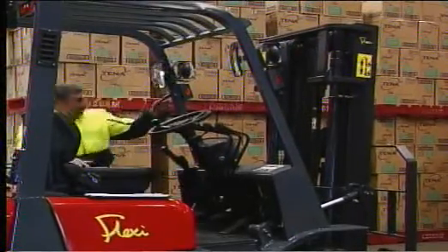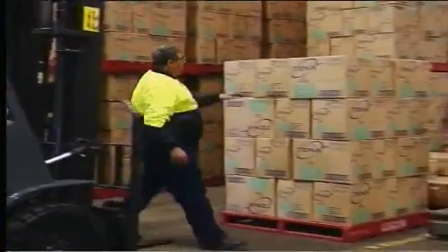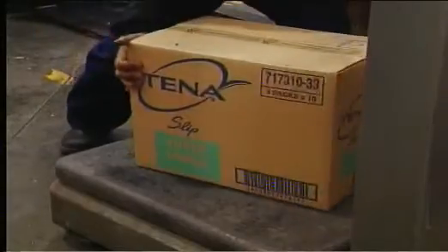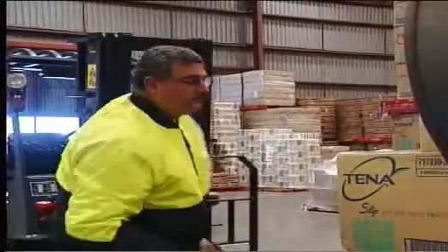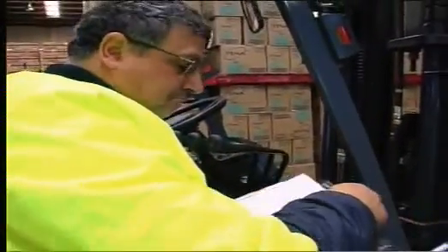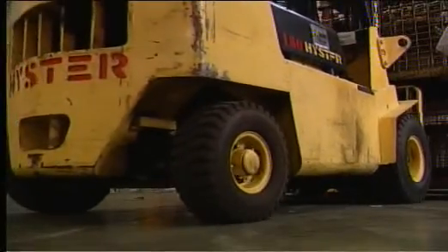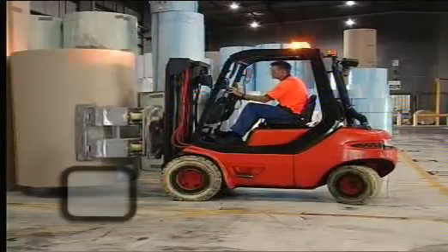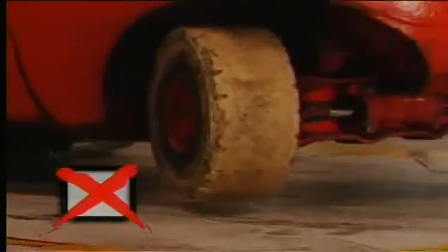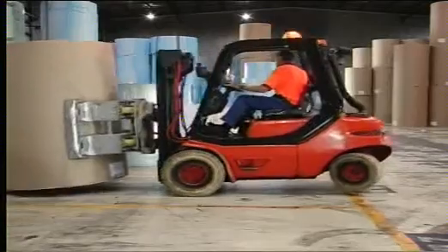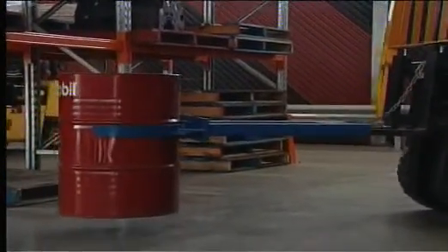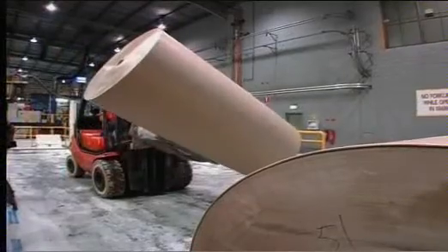You must understand the weight of the load to be handled. Weigh your load, check the paperwork, or calculate the weight by breaking it down into individual units. Your load must weigh less than the capacity indicated on your forklift's load capacity plate. Forklifts are often unwittingly operated at the edge of their stability envelope. If the back wheels lift from the ground, your forklift will be many times over its safe load limit. Attachments are used for unusual loads and will change your forklift's load capacity due to increased weight.